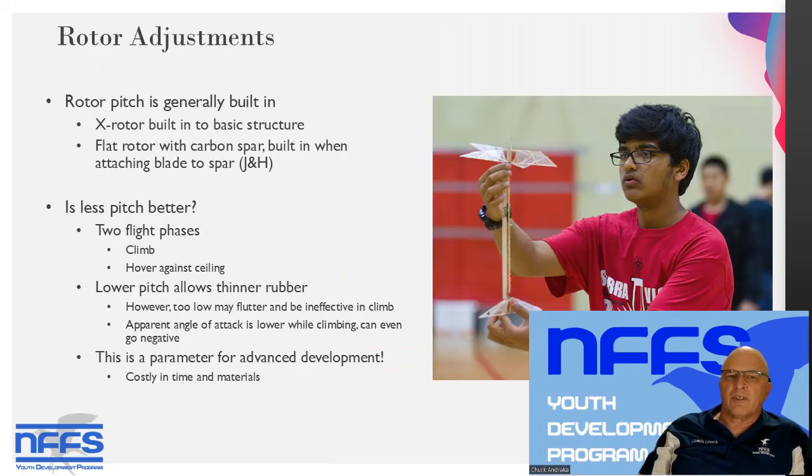Rotor adjustments. This is more advanced because your rotor pitch is generally built into the rotor. The X rotor, it's in the basic structure. A flat rotor with a carbon spar, such as the J&H helicopter, gets its pitch built in when you're attaching the blade to the spar using the fixture in the kit. So making rotor adjustments might mean building a new rotor or cutting into the rotor.